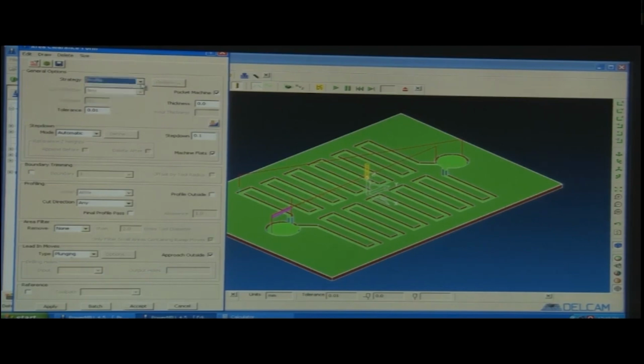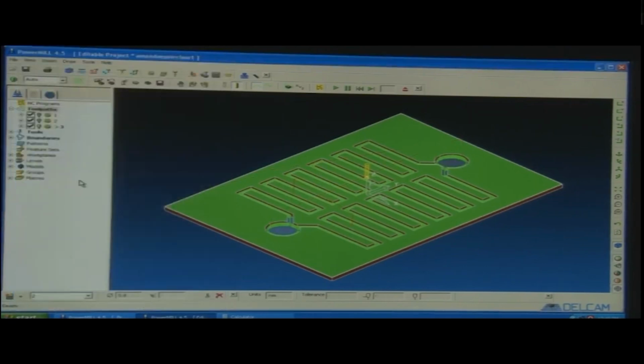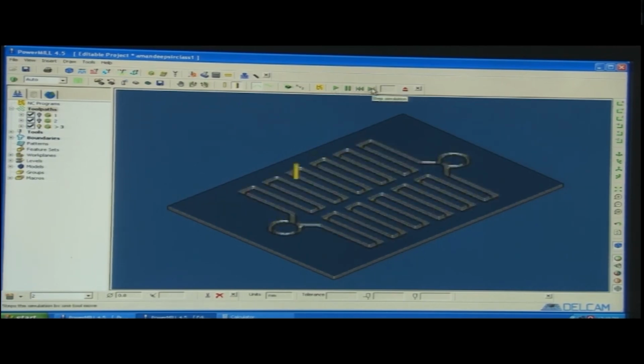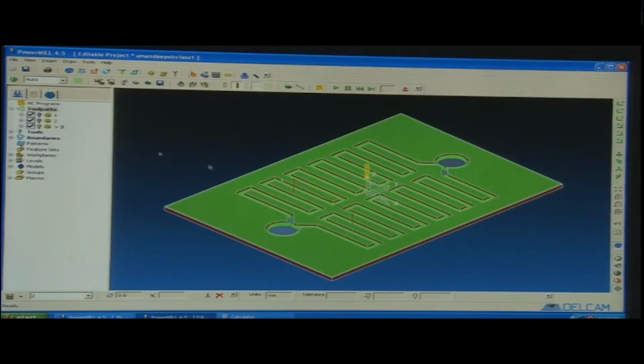Okay, profiling is also one of the options. When we say profile here, how does profiling happen? When I say profile, it will machine in this way. You can see it will start from one point. It is just making a linear movement. This is known as profile or profiling. Okay. In one go it has completely machined. It is not taking care of the stock, this round stock, the waste material that will come out, it just makes the profile. So, roughing, profiling and finishing, the three modes.